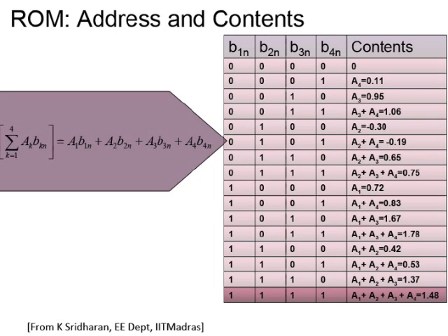What about the voltage that will be stored across the capacitor? Because now these capacitors are not leaking. No. So yeah, we'll discuss that when we get to the static memory. You are absolutely right that at the end of the day, even information has to be stored as charge on the capacitor. But the structure of the circuit is such that there is always leakage. You cannot avoid leakage, but that leakage is compensated in a way where the information is stored. The voltage across the capacitor doesn't degrade. It is held static, but there will be some leakage.